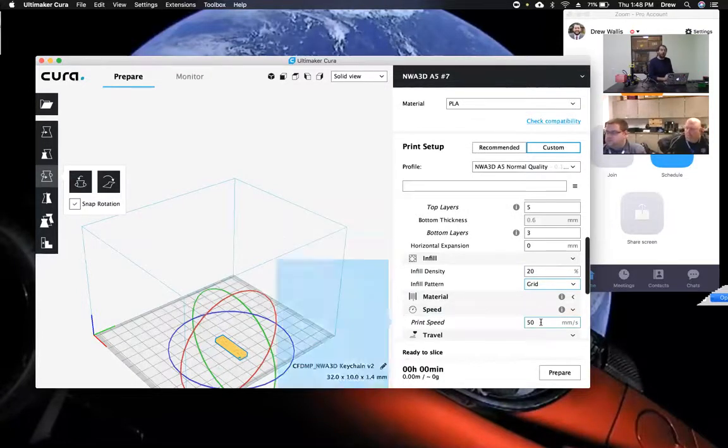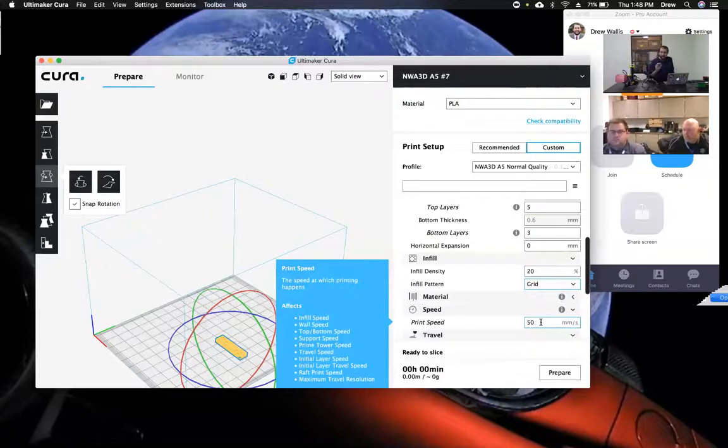And then a note on the print speed, 50 to 60 millimeters a second is as fast as you can reliably print. So these can print like 3 times faster than that. But if you crank them up to print really fast, they have a tendency to fail more often because it's just the chemical process of the layers binding together. If it's going super fast, they might not adhere together really well, and that could cause you to knock your model loose or your layers not to stick well and stuff like that. So we like to err on the side of successful prints. So we go to 50 to 60 is pretty much the maximum for any material extrusion 3D printer like this.